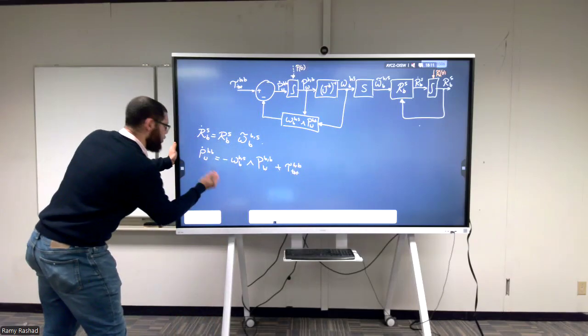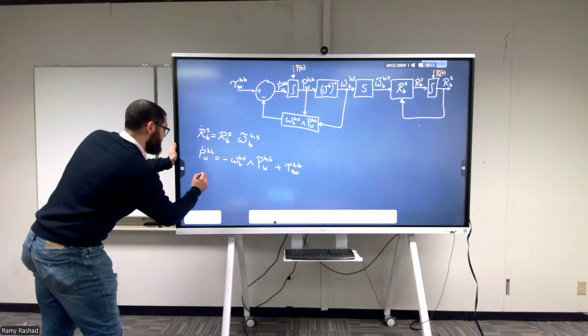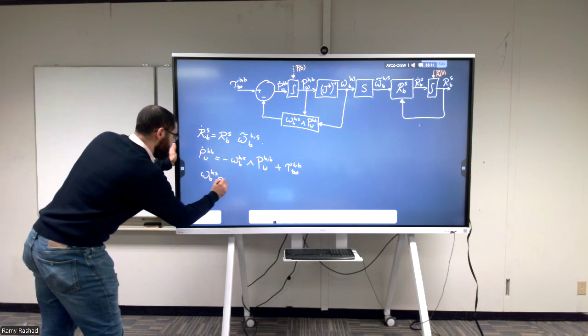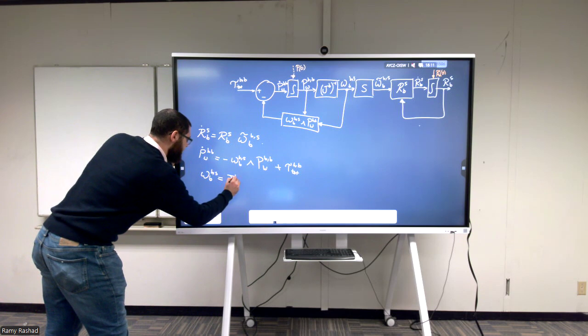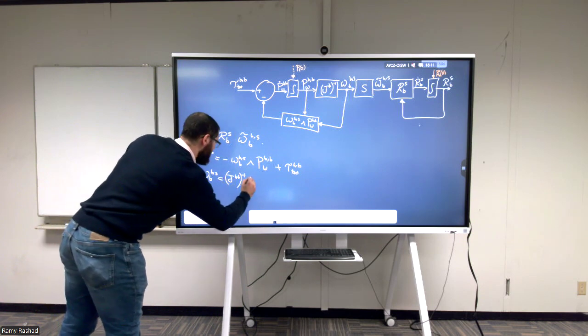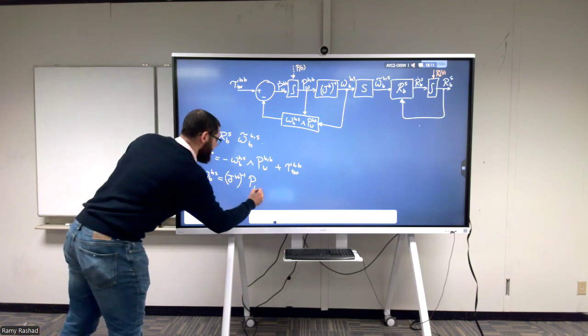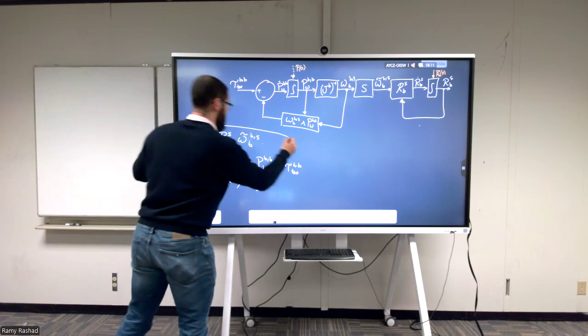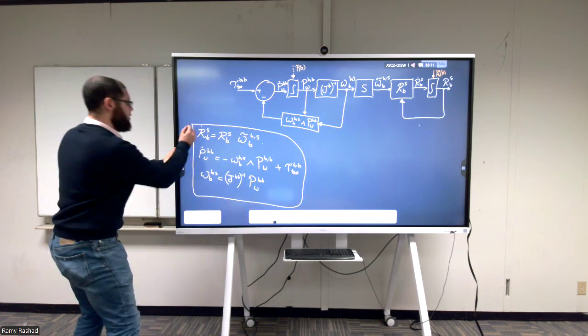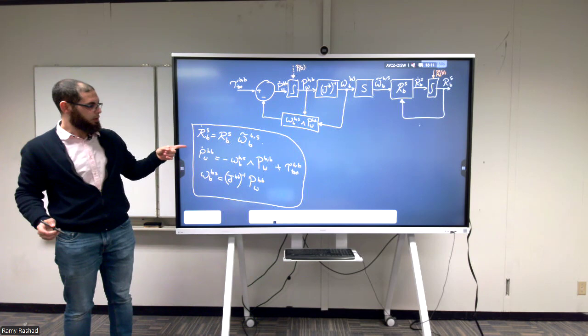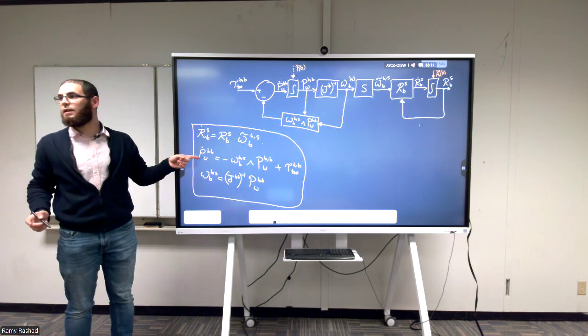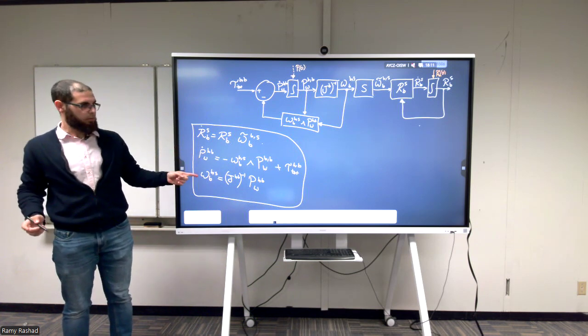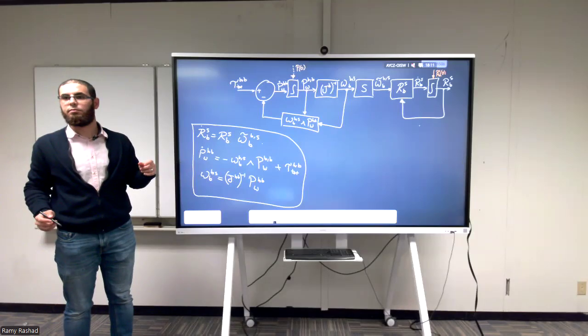And then we have the constitutive relation, which simply says that the angular velocity is nothing else than the J of B expressed in the B frame, inverse, multiplied by the angular momentum in the B frame. So kinematic equation, momentum balance, constitutive relation. Easy?